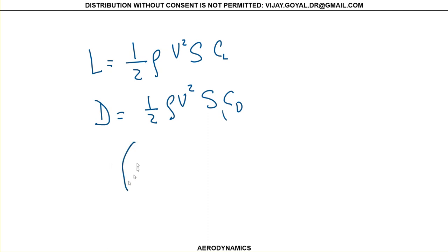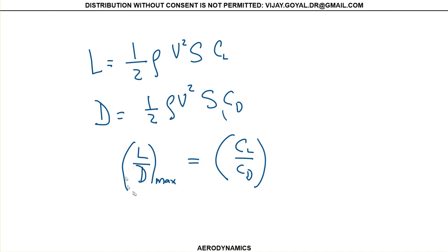And what typically we have in this quantity that's very, very important is that we can also write this as CL over CD. This comes from testing, and typically we want to make sure this is maximum. You can immediately see that your D can never be 0, otherwise this will blow up. There's always a D. There's going to be a sacrifice that we need to make. And actually, your plane would not fly without any drag.